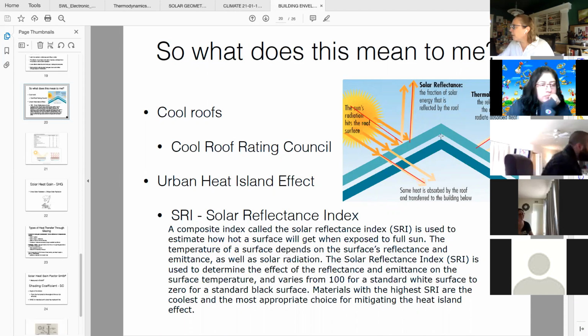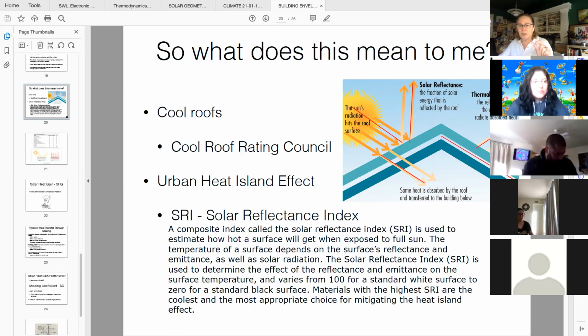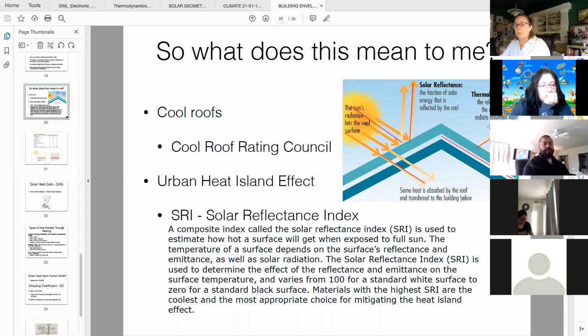But a radiant barrier is a highly metallic, shiny thin layer, maybe a 32nd of an inch, that in certain circumstances in your roof assembly, if you install it, will help reduce conductance of radiation coming through the material and will increase the emittance back to the atmosphere.